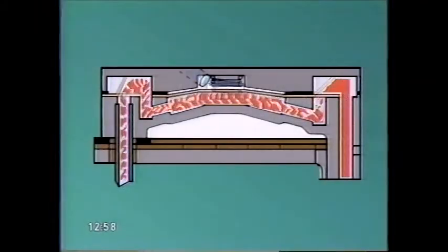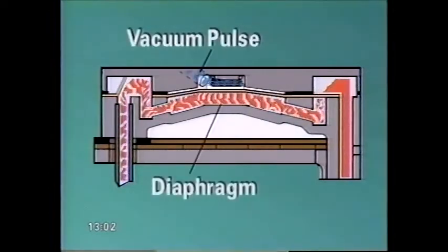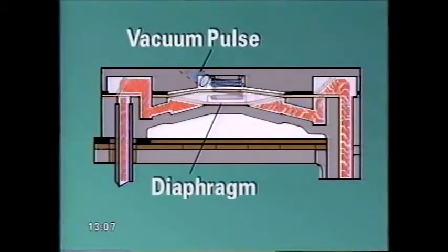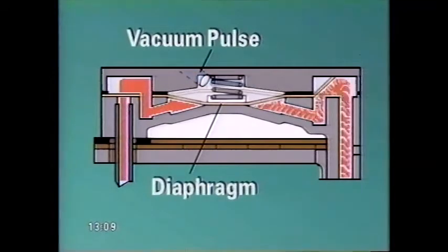The principles of operation of the fuel pump are the same as those described earlier. A flexible diaphragm is driven by vacuum pulses received from the engine. We'll have more on the operation of pulse pumps during diagnostics later in the course.